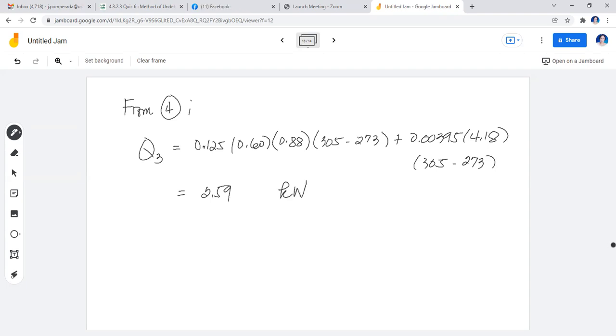Still having the unit of kilowatt. Okay, we're done with Q3. We go to Q4. What's Q4? The leaving air, the exiting air from the dryer. So then it will have mCp delta T, again dry air, plus mCp delta T, water vapor. Okay, that's for our Q4.